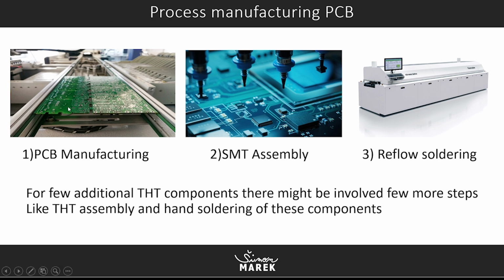It starts with the manufacturing of the PCB itself, the board. Once you have the PCB manufactured, you can move to SMT assembly, where you put your components on the PCB and place them properly, and now you can move to reflow soldering, and this is your SMT board actually